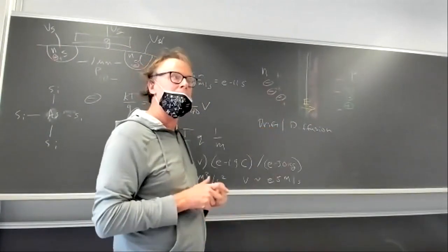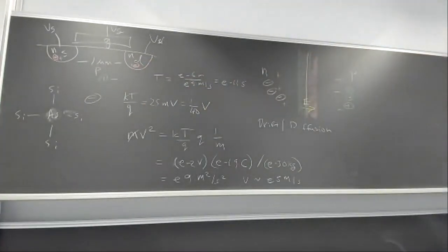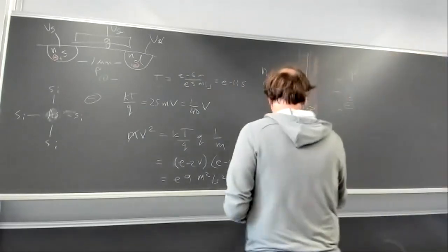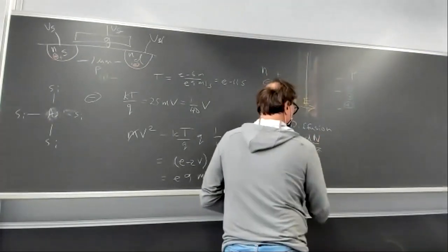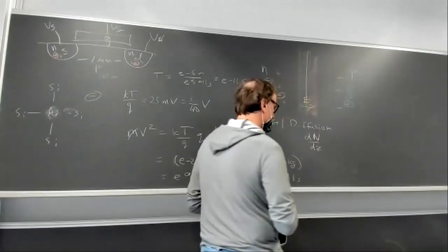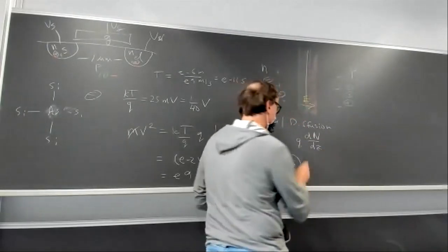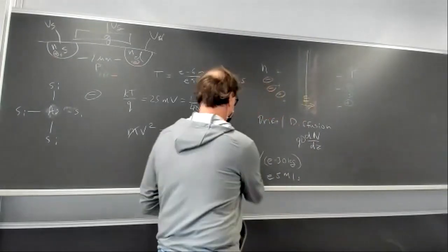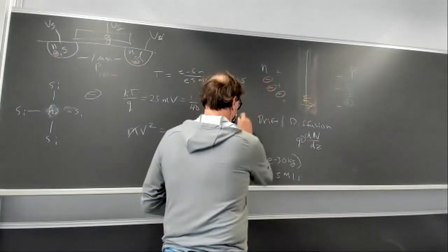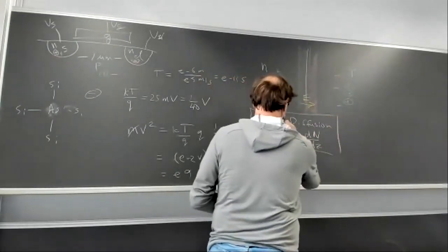Okay. Can you repeat what's the diffusion working when there's a... There's a diffusion current anytime there's a gradient of concentration. And it'll be proportional to Q, the electric charge, because you have to get units of charge out of it, times some diffusion constant. That's the flux. Or the current, I guess the current density, due to drift and diffusion.